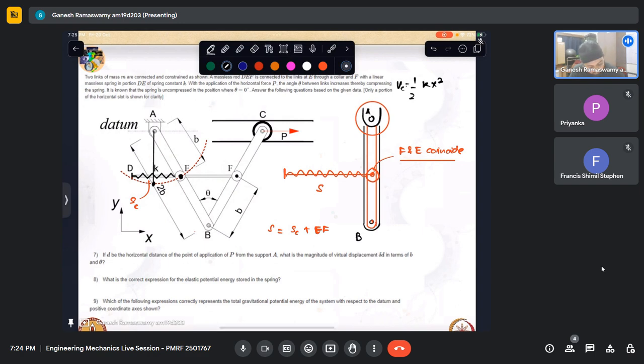This change in the spring potential energy will be 2 kx by 2, which is kx, which is again the force. So since these are conservative systems, we have recast all the forces as some potential energy, and we are solving it by that approach. This becomes easier in certain class of problems. That is why we are doing it. But nonetheless, one should practice how to do it by force method, by energy method, and get the fundamentals clear.